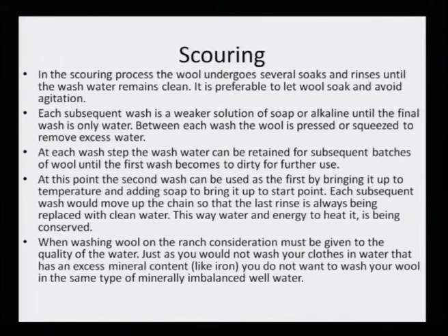So, because there is so much wool that needs to be washed, these washings need not be thrown. The second wash can now become the first wash in the next batch by replenishing it with a little more of the soap solution and raising the temperature to 60 degrees. If this is maintained, then the same washing bath can be used again and again till it really becomes dirty, and then it is time to discard.